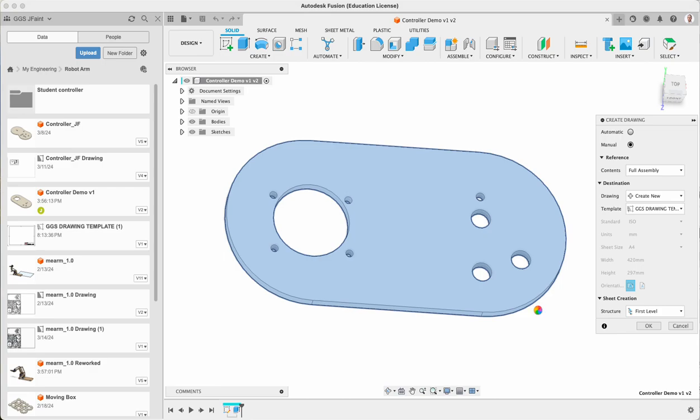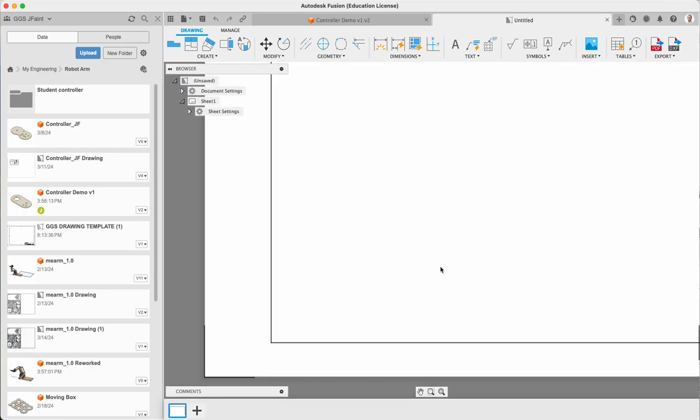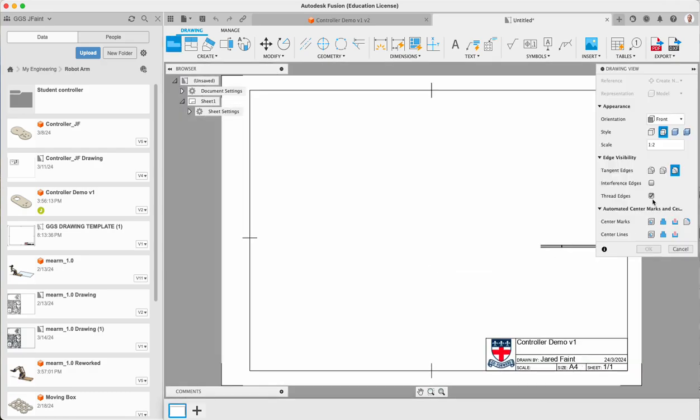And then this often takes a moment. So it'll then load up the drawing panel. And then there's a few things that we need to do once this sets up so that we're ready to be able to develop our drawings. So you can see by default, it's given us an item to upload. The general format that we want to have is the thing that has the most detail goes as what we call the front view.